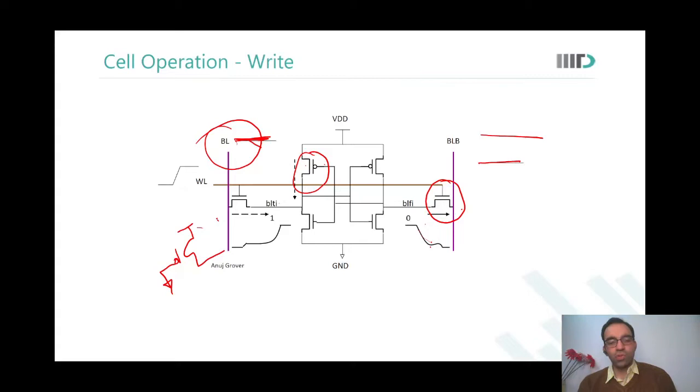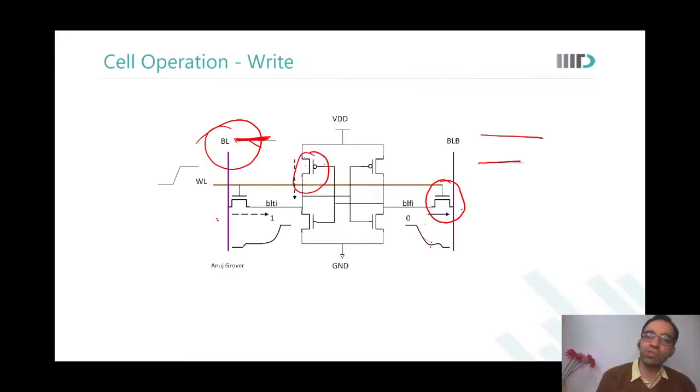Okay. So we are almost at the end of the class. What I will do is I will just introduce. So what we did see over here was that in a 6T memory cell, there is some ratioed thing that is coming into picture. There is this PMOS that is sinking some current, there is this NMOS that is driving some current, and so on. So there is a ratio thing that will come because we removed those 4 PMOSs in the first step, because of which there are certain figures of merit linked to a memory cell.